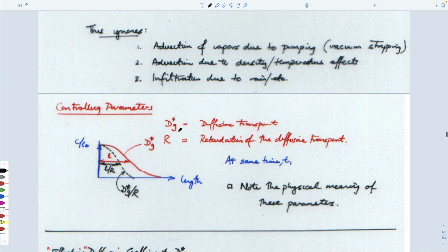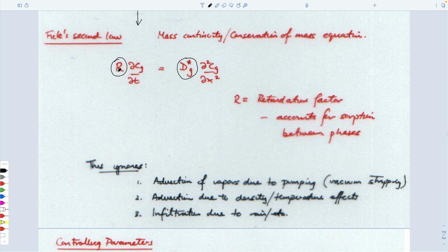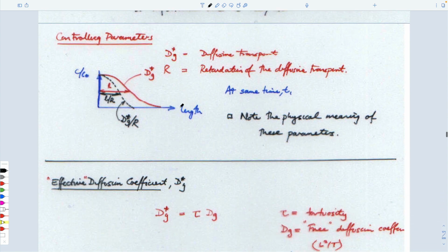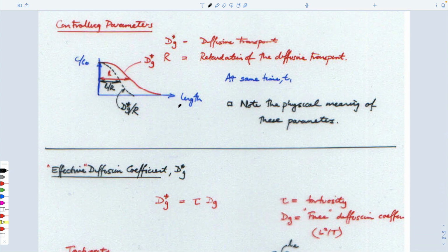And so we can think of the retardation coefficient in exactly the way that we did before. We could divide both sides through by retardation. And we also did it before with an advective term, right? We won't do that this time. But it certainly defines that the rate at which the diffusion can occur is reduced by the magnitude of this, which is bigger than 1 and less than infinity. But we don't know exactly what it is yet, but we could assume that that's the case.